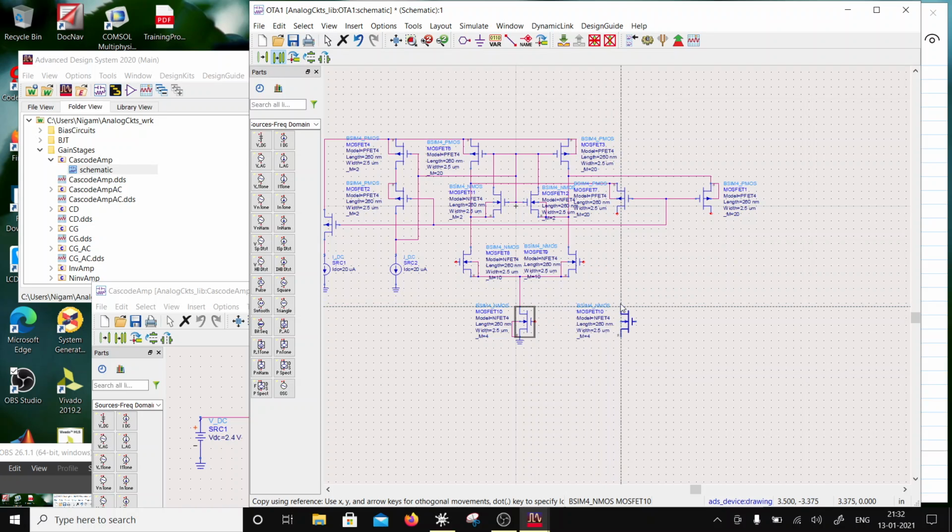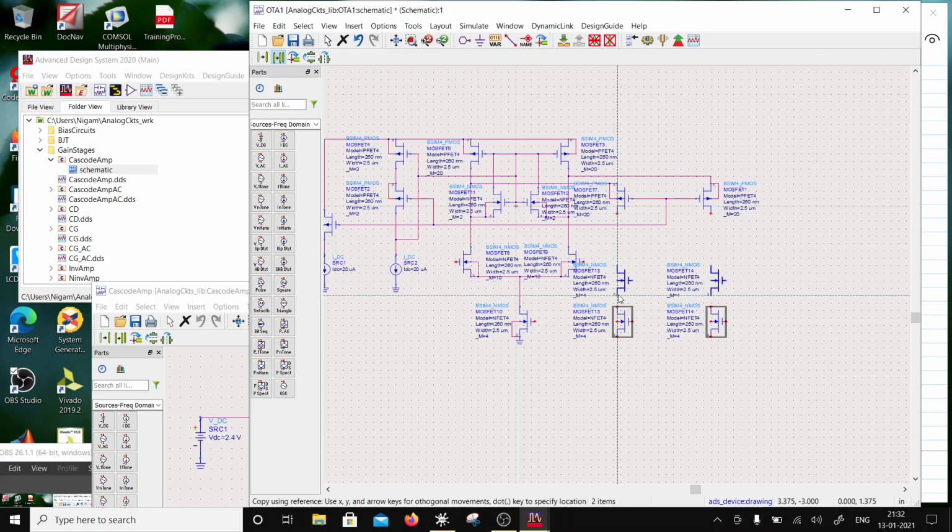Over here I have repeated this transistor, and again for the other leg I'm going to repeat the same transistor, right? So this is repeated here, and then I'm going to take that and repeat it to be a cascode like that, correct? And this one I am going to do twice the size, 8.